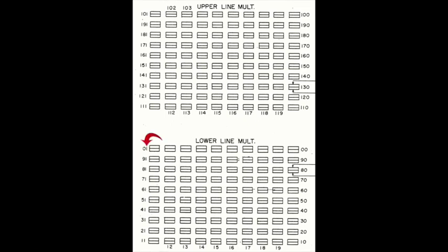The units digit of the line circuit terminal number is its rotary position number. For line circuits whose tip and ring leads are assigned to the middle bank tier, a hundreds digit of 1 is added to the terminal numbering scheme.